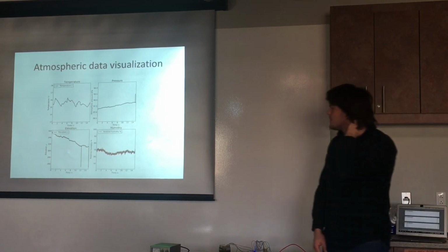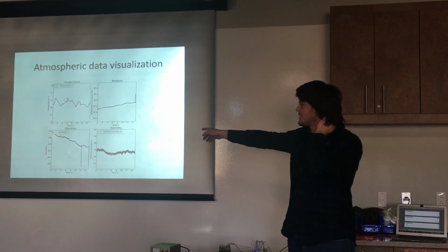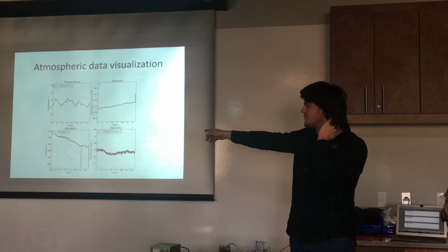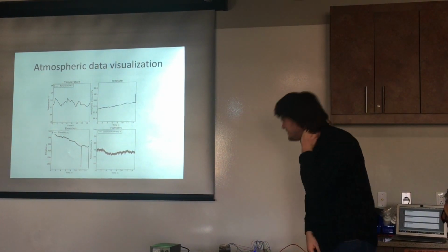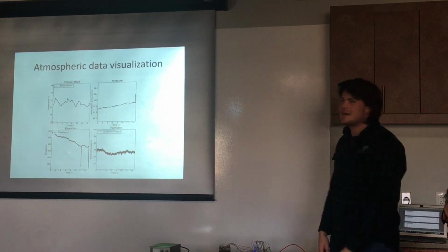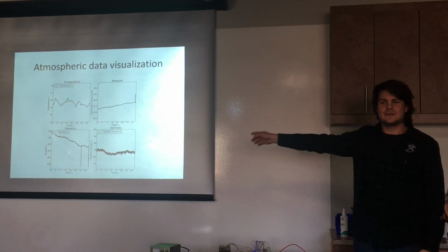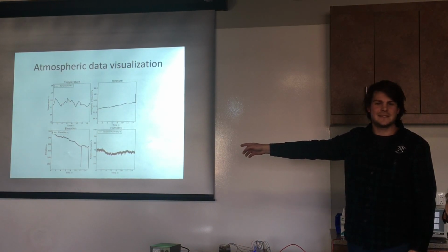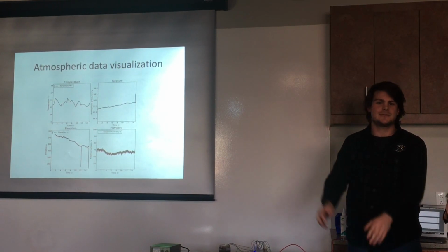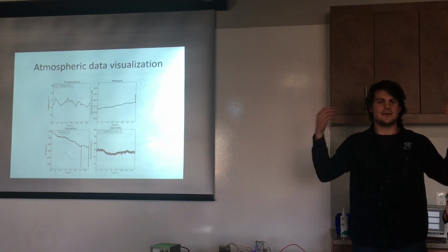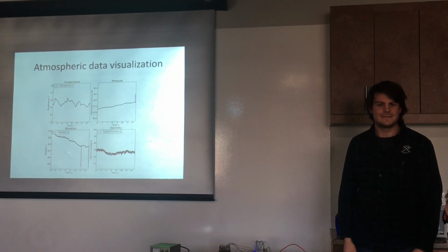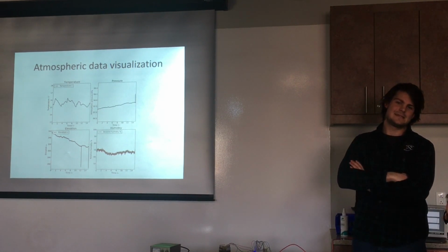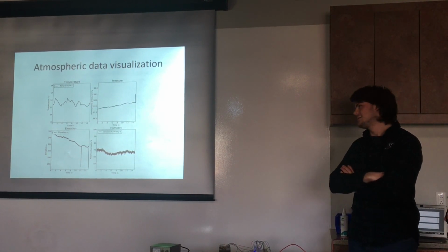Well, so that's what I thought, right? Lower elevation, higher pressure. So then, how does it deal with, because this can resolve things to just pascals, like single pascals, how does it deal with a low pressure system coming over? Do you just suddenly go up 10 meters? You either know your elevation and you get atmospheric pressure, or you tell it what the atmospheric pressure is and you get elevation. They're fundamentally linked.